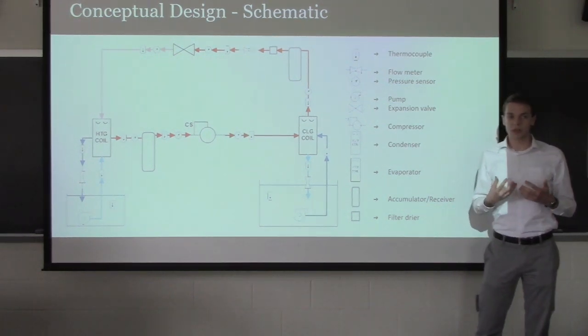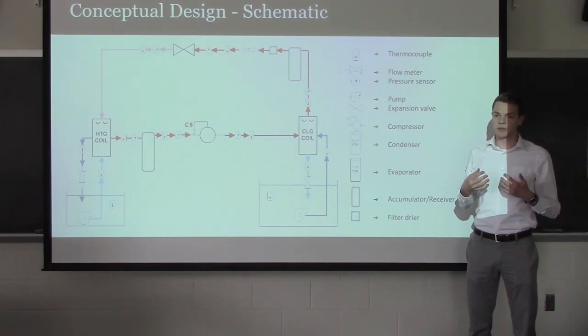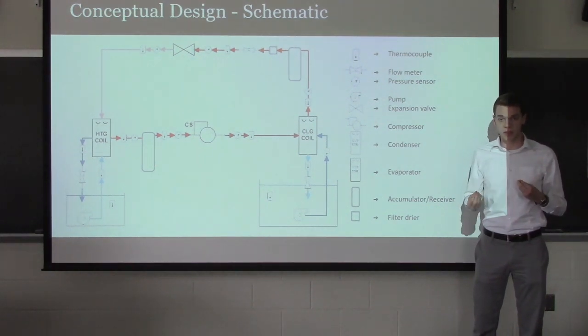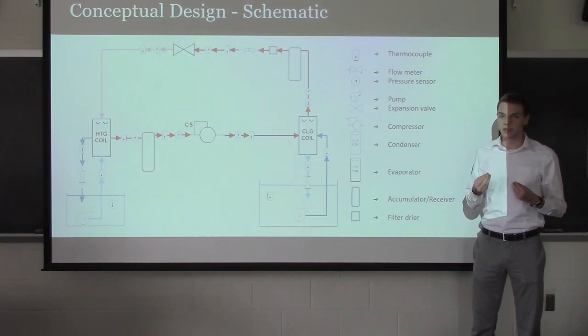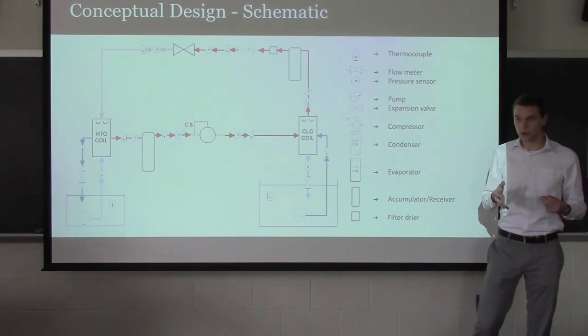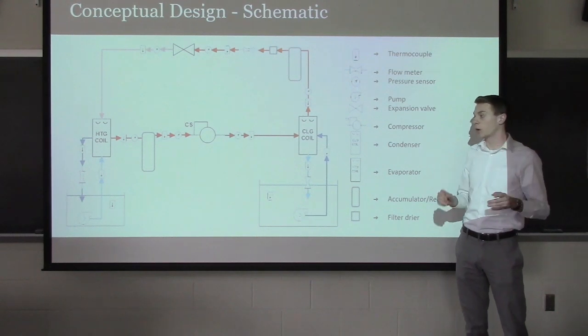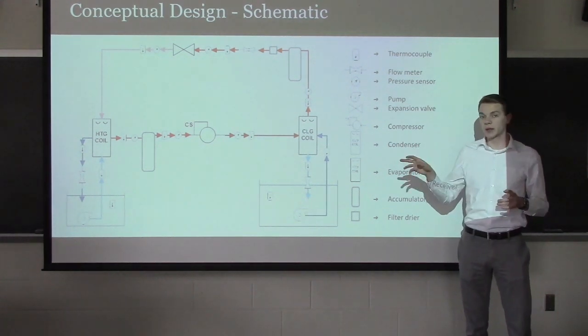But for ours, we decided to use water due to the lab room having large differences in temperature and typically humidity here in Pennsylvania, that it could lead to inconsistent lab results. So with water, it's usually room temp and it's very consistent, doesn't alter due to atmospheric pressure. Now there are two pumps that pump water through each the evaporator and the condenser.